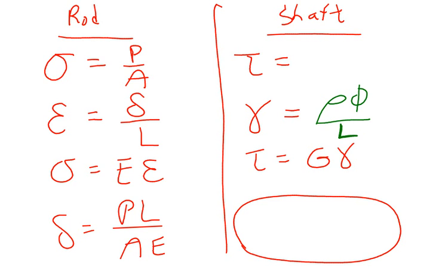And that should be something that's intuitive, because if you've ever seen a shaft that starts to crack, because there was too much load, too much torque applied to it, where does it start to crack? It cracks on the surface, because that's where stresses and strains are largest. So that's our equation for phi.